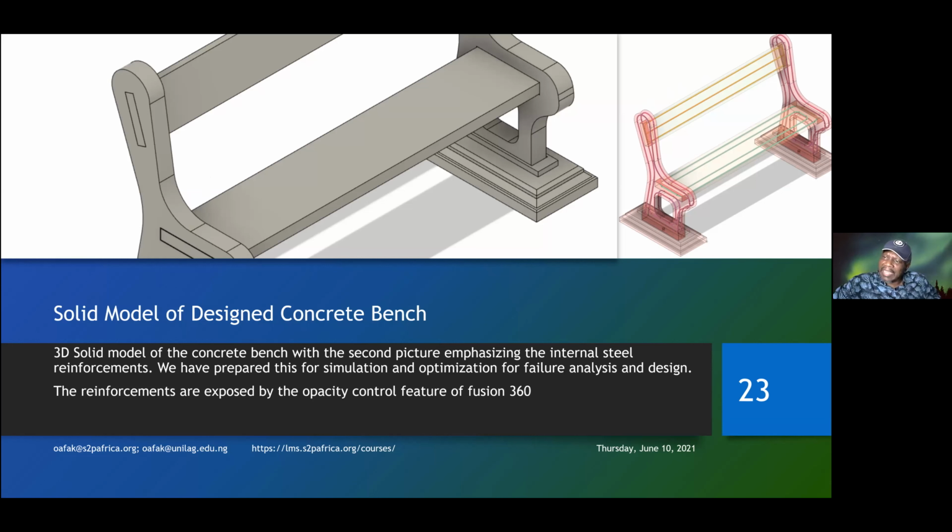And then the next stage is to put this through a simulator where we put maybe 3 people sitting on this, put their weights on it, and see how those weights will be resisted by the support, by the benches, the backrest, as well as the support, and see how close we are to the factor of safety, using static loads. Later on, we can try dynamic loads. Then we can be sure how far we are from failure, and then we apply a particular factor of safety. These are not things that your artisan will be able to do.